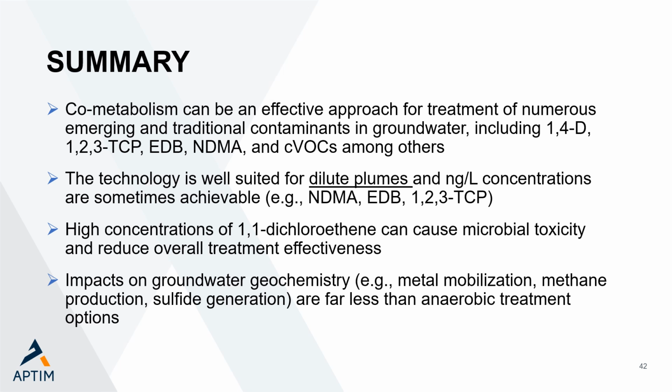The other thing I didn't talk about very much today, but that's pretty important, is that the impacts of this technology on groundwater geochemistry, things like metals mobilization or sulfide generation, are a lot less than anaerobic treatment. This approach has really progressed a lot over the last 2 or 3 decades, and it's really widely applicable now for treatment of a variety of dilute plumes, which tend to be a major issue these days.